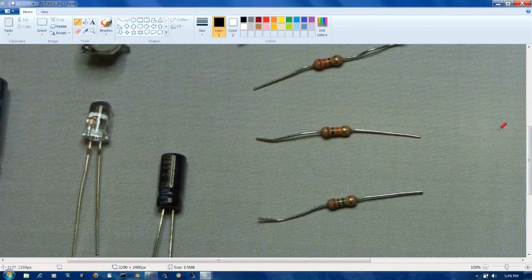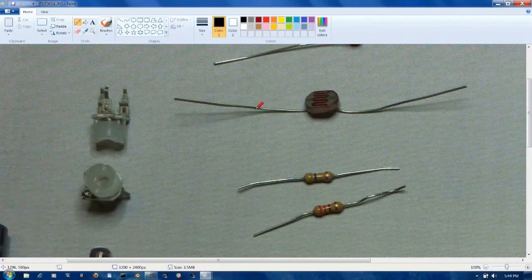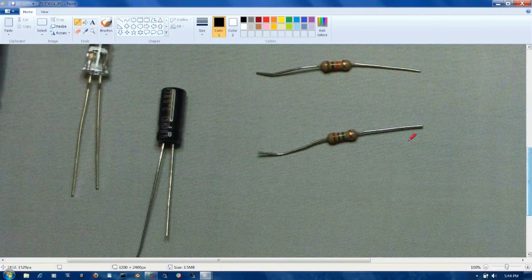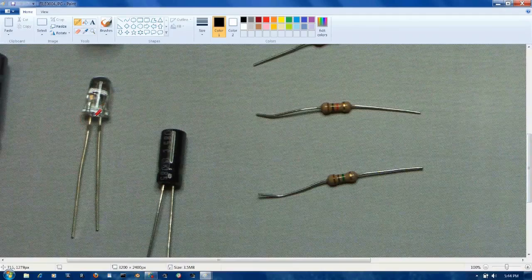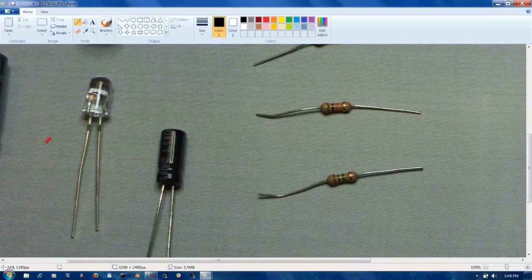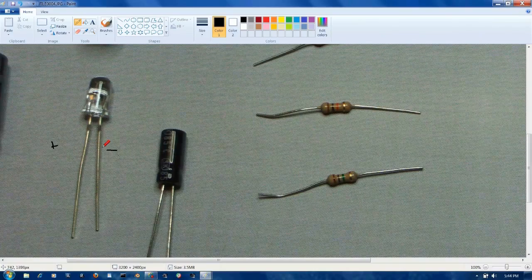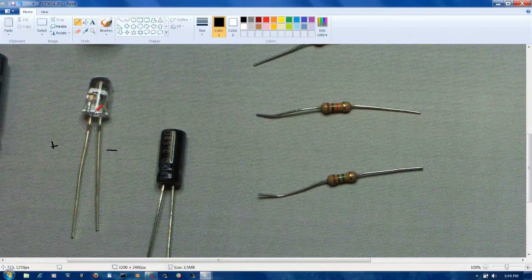This is an LED. Oh, by the way, these have no polarity. It doesn't matter which side you put positive and which side you put negative. These, of course, have polarity. This is an LED, and the longer end, notice how the ends are almost the same size, but the longer end would be the positive side, and the shorter end would be the negative side. And let's say you took this component out of a previous board and wanted to reuse it. Well, there's another way to tell an LED. On the negative side, this is round all the way around, except there's a flat side right here for the